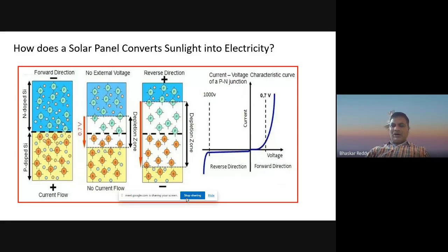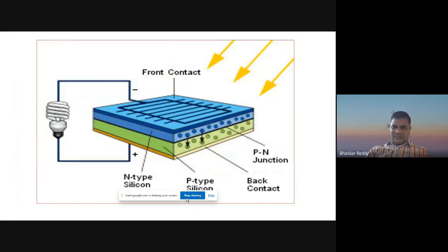So I have one layer called the p layer, and one other layer called the n layer, made of a semiconductor material. Now I am taking silicon. The p-type is manufactured from silicon semiconducting material, and the n-type is also manufactured from silicon. I already said there are holes as majority carriers in p-type, and electrons as majority carriers in n-type. And I am sandwiching, combining them together.